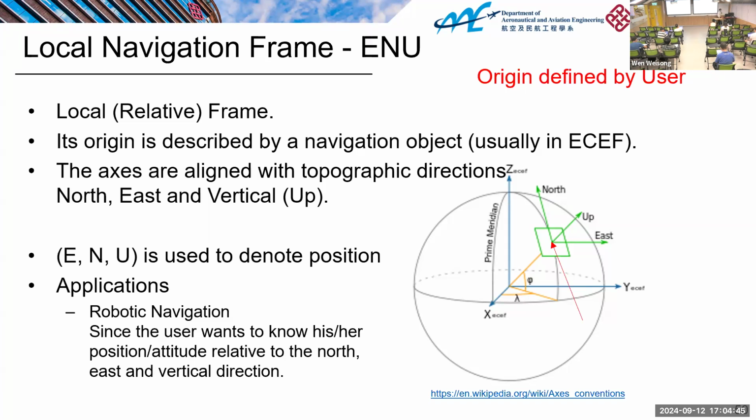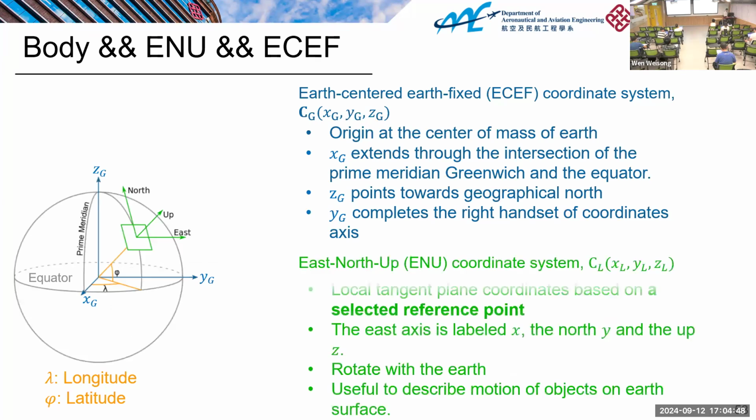Okay, so if we put the three coordinate systems together, of course, one more time. The first one is the body frame, right? The second is the ECEF frame, fixed to the center of the Earth. This is the ENU frame, with respect to the tangent space of a given point. This is the center of the Earth, and this is the longitude and latitude, which are angles with units of degrees. Then the east, north, up directions: we usually call this the local frame.